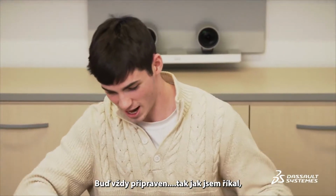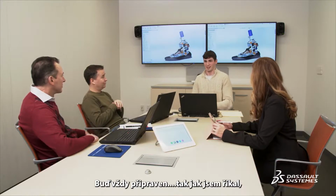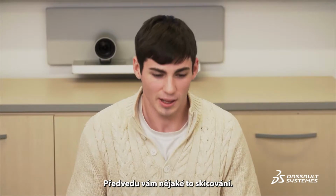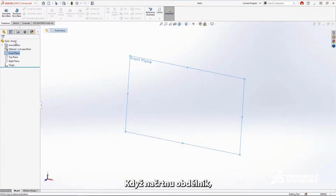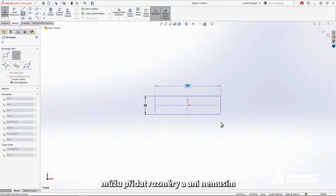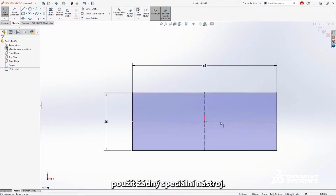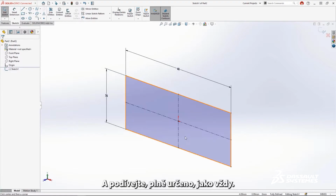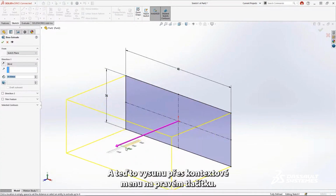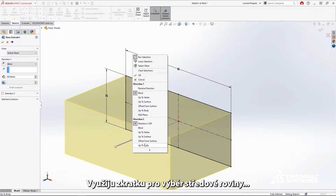Okay. No problem. Gotta be prepared, right? As I was saying, this is new, but it's still SolidWorks. Let me show you some sketching. After creating a rectangle, I can add a dimension, and I don't even have to use the dimension tool. And check it out, fully defined every time. Am I right, guys? And now I'll extrude it using the right-click menu. I can shortcut to selecting a midplane.